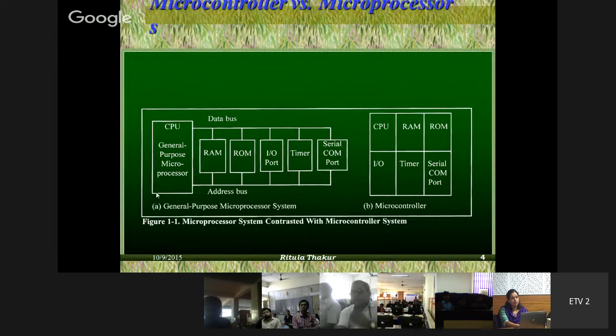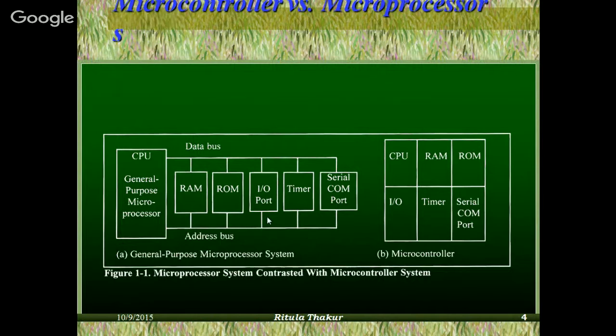So अगर हम एक layman को समझाना है, who is not an engineer, he just wants to ask me that what is the difference between a microprocessor and a microcontroller, I can tell him that whereas a microprocessor is a CPU on a chip, our microcontroller is a computer on a chip itself. ठीक है? So this is the main difference between a microprocessor and a microcontroller. And this picture, it is depicting whatever I have told. As you can see here, in this case, this CPU or general purpose microprocessor is a heart, and then you have RAM, ROM, memory, input output ports, that means PPI chip, timers, serial ports, etc. All of these are externally added to this CPU, and that makes it a complete functional unit. Whereas in case of a microcontroller, all these components are embedded on a single chip itself.